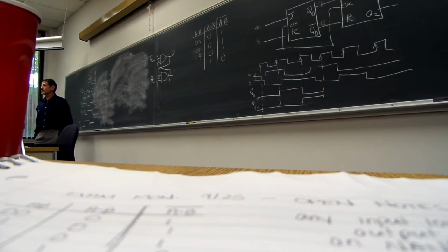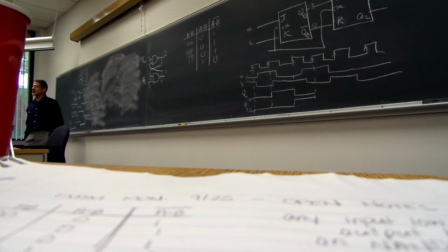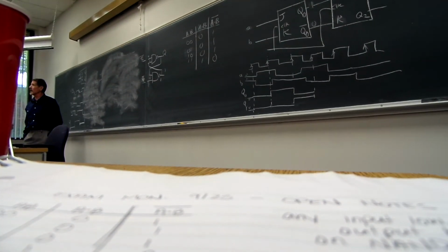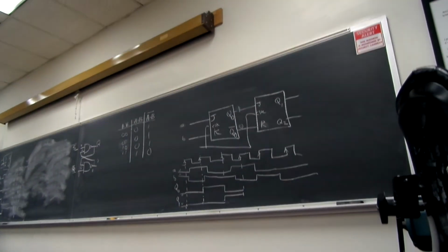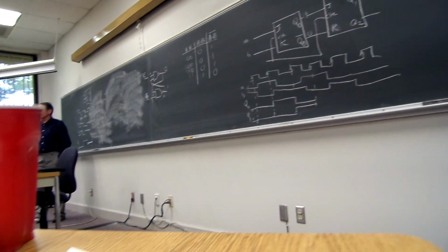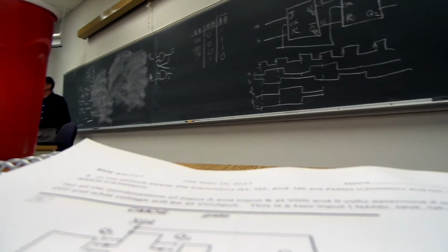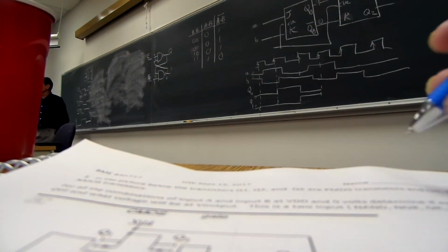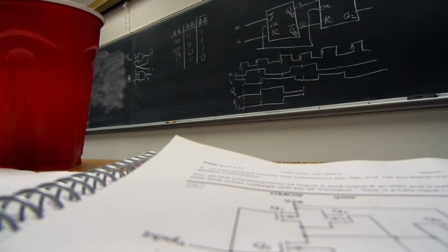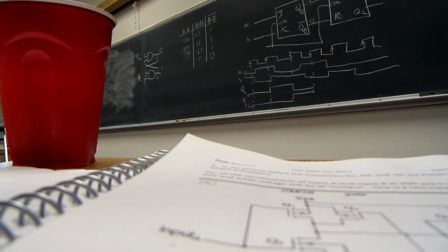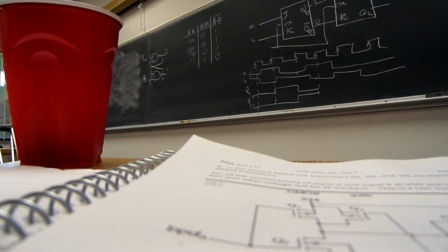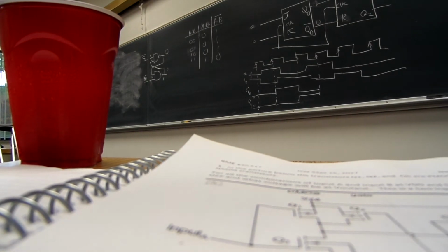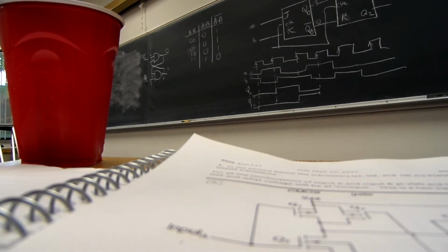Questions at all? Okay, the top one is trying to have you figure out what kind of a gate that is. So just as a review, if you have an NMOS gate, the gate to source voltage is high. Is the gate on or off? You were very positive about that, but you're wrong. With the NMOS gate to source voltage high, the gate is on.